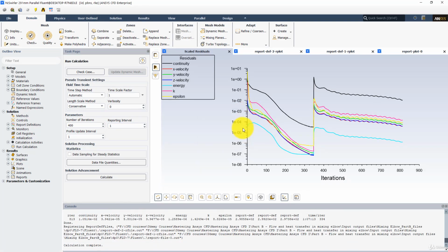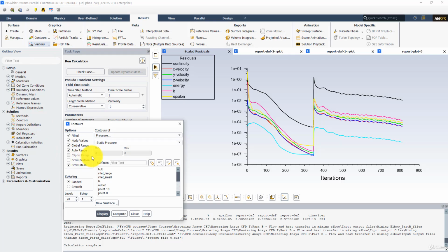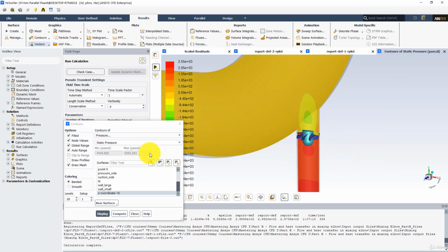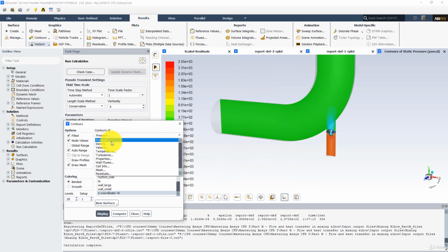And now I will close the Fluent window, but maybe before that we can analyze the results inside Fluent as well. So I can see the results of, let's say, the pressure on the mid plane or the symmetry plane. And this is the pressure difference here. And the second thing, okay, just make it local. Second thing is the velocity contour plots.